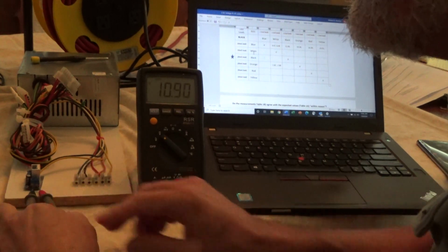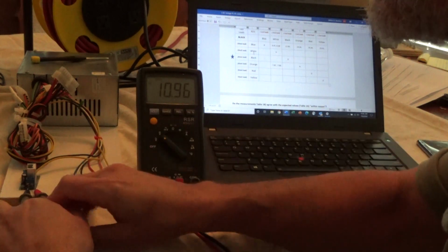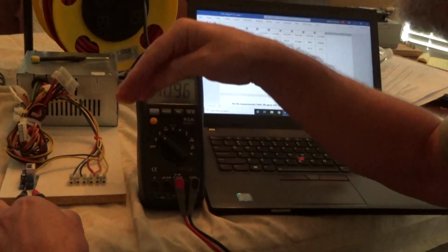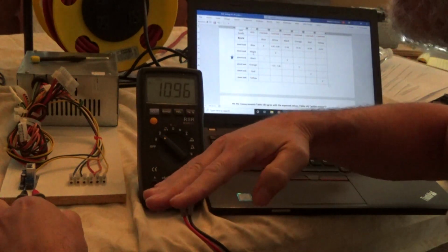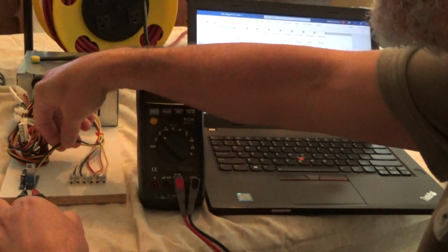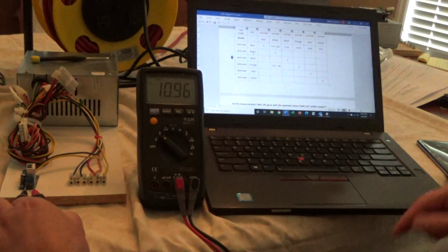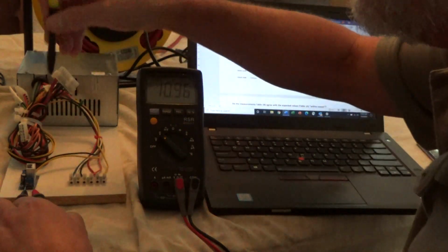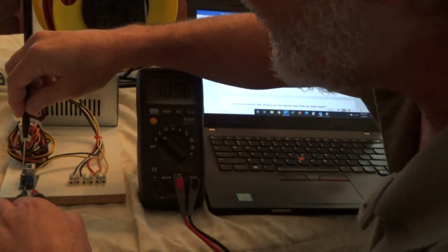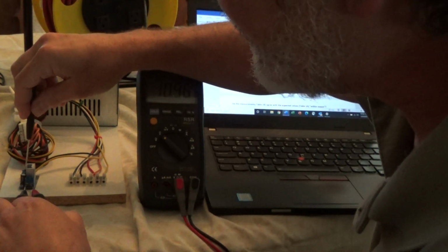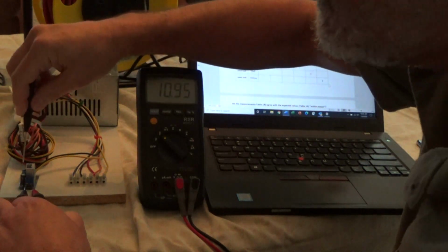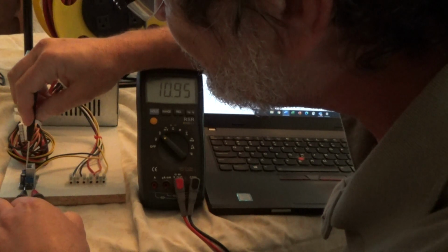Now, notice that that's about the largest voltage you can get out of it, because when you're regulating voltage, you get a drop down from what's available. So we know we have about 11.9 volts here. It drops it down about a volt. That's called a dropout voltage. But check it out. There's a potentiometer on here. That's a variable resistor, and you can take the potentiometer and adjust it. It's kind of a pain. And watch, basically you can control the voltage.